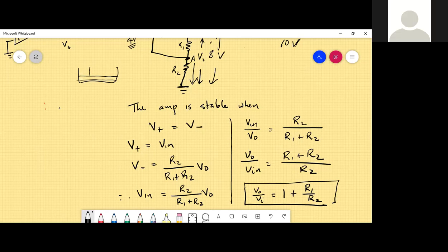Sir, in regards to this particular circuit, are the two resistors normally equal or can they be of different values? R1 and R2 don't have to be the same. It's very rarely that they are the same. And I'm saying to you now that it can be a capacitor, an inductor, it doesn't matter, because if it's Z, it's the same thing. All we do is write down the value in the S domain and proceed.